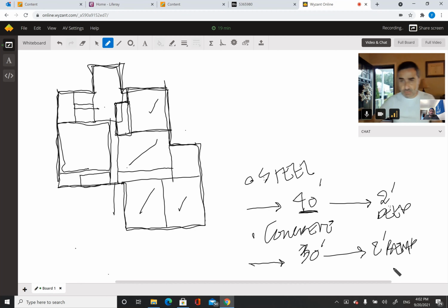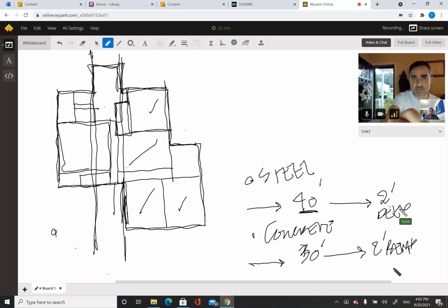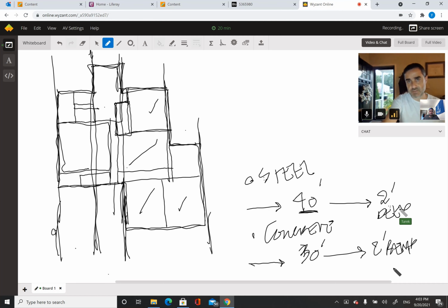So you start with a grid. I want to pick somewhere where you don't start like, I'm going to start from this corner or go this way. You don't start like that when you start to draw a grid. I start at the most important places, somewhere here. I don't want columns here, so maybe that's one column grid here. That's another one, and that's another one. And I could do this, that's one column grid, and this one. So now I've laid out a hypothetical column grid in this direction.